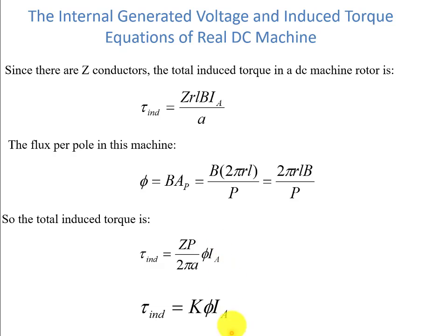And similarly here, if we increase the IA, we can visualize this mathematically that torque induced is proportional to IA. But if it is a motor, then we are supplying this IA, so it's impossible that we can increase the IA to infinite and get infinite torque out of a machine. So obviously again we have those certain limitations of the saturation and all those things, so we cannot have infinite torque produced in the machines.